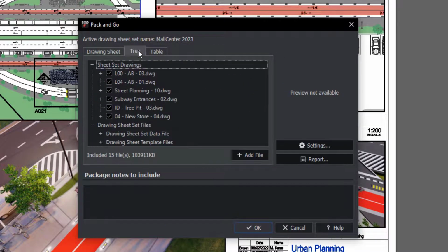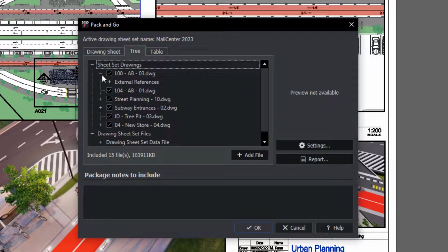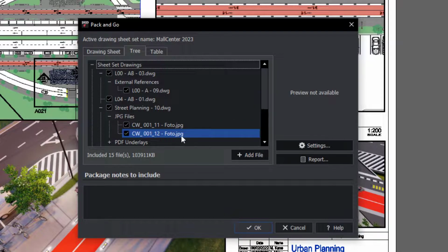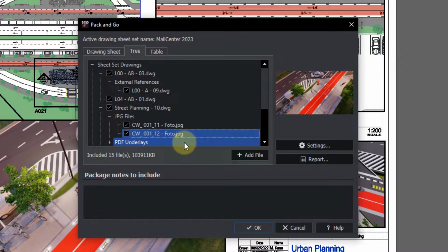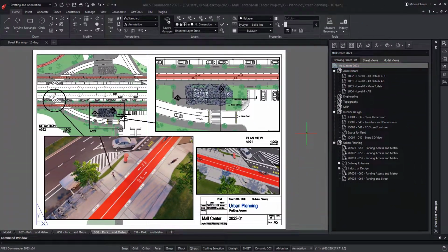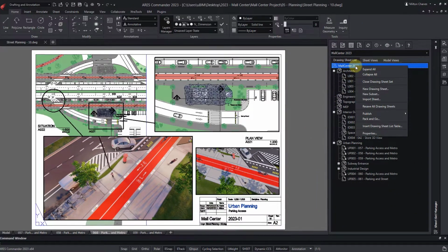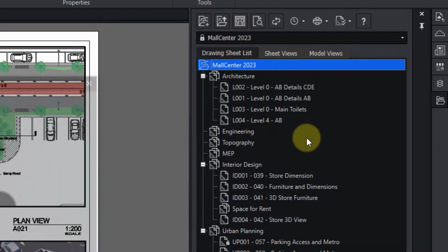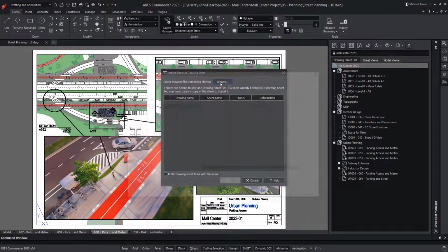With this, it will generate a file structure that could be more complex, depending on the number of sheets configured in the different files that are part of the sheet set. But before exporting the entire project, we are going to make a few simple changes, which will remind us how to add a sheet already configured in a file.